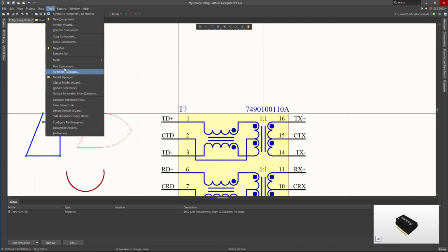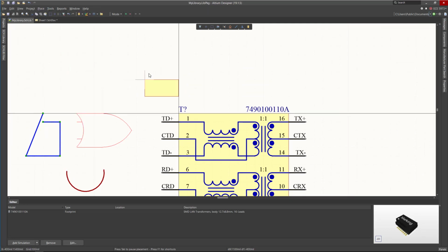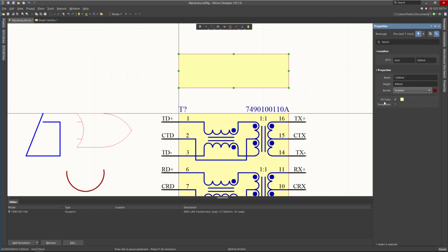and also you have place rectangle. This will be used more often to create integrated circuits. As you see in here, basically this is a rectangle, and you can click on it. You can change the properties for that. You can change the fill color. You can make it transparent. As you can see in here, it's transparent right now, where you can see the grid through it. So here you can see the grid through it, and this one is not transparent. And you can control the thickness of the border lines. So make it large, for instance, it's very thick. You can change the color for that.